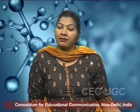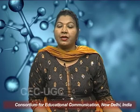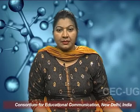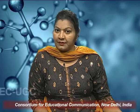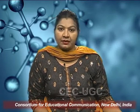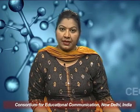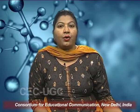Next, we can find out what the linearity is between the current passed and the voltage we are getting. So we can get a linear graph between the current we are supplying to the semiconductor and the potential developed, that is the Hall voltage. So there is a linearity between the change in the current and the development of the voltage. And what are the applications of the Hall effect?